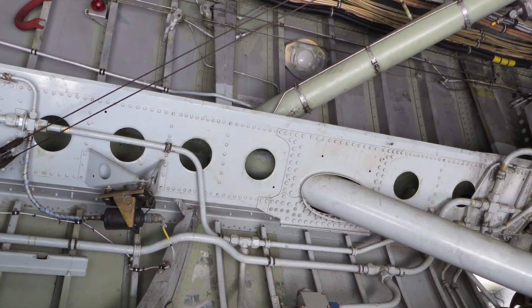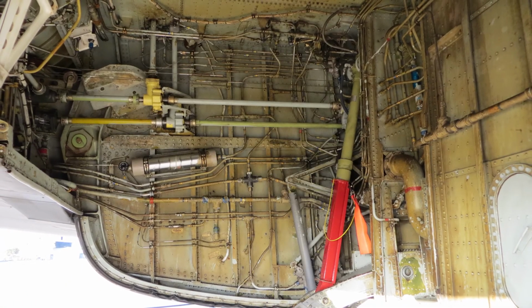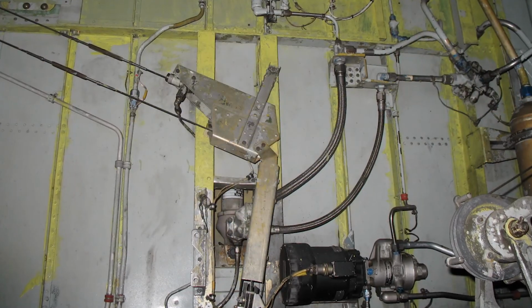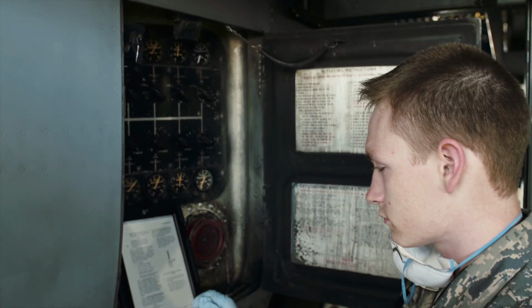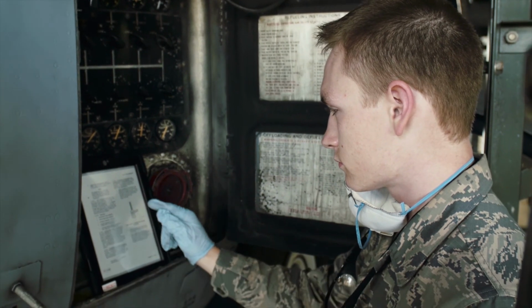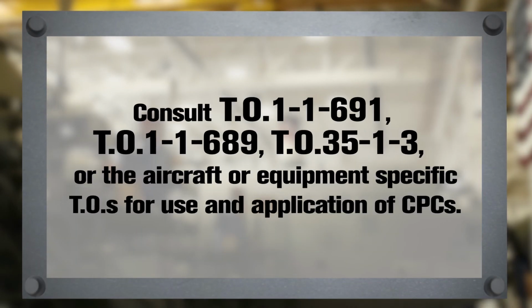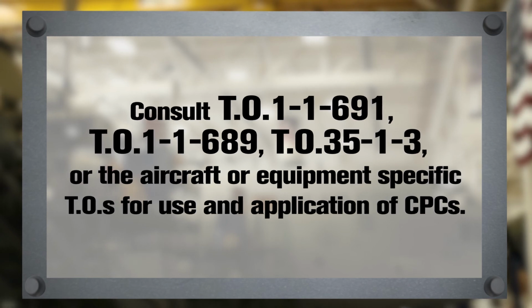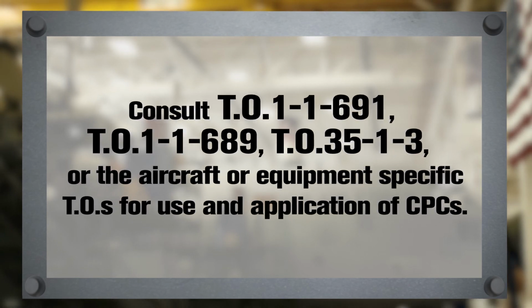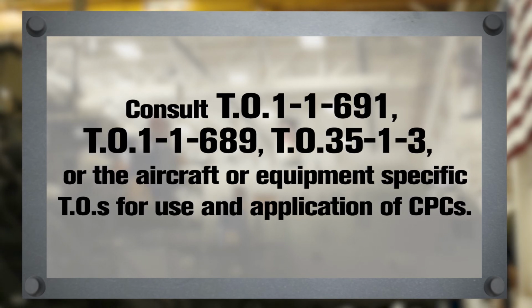Corrosion-prone areas or surfaces where paint has been damaged should be routinely protected by CPCs until a more permanent treatment, such as paint touch-up or sealant, can be applied. There are many types of CPCs used specifically on aircraft components and equipment. Consult TO 1-1-691, TO 1-1-689, TO 35-1-3, or the aircraft or equipment-specific TOs for use and application of CPCs.